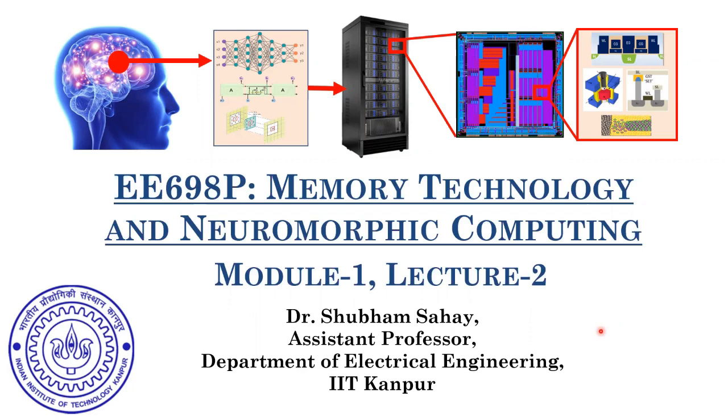Now, going ahead, we also talked about how the memory is organized within your conventional computing systems, such as your CPUs. We saw that, immediately inside your processing core, you have these fundamental units of memory, which are known as registers. All the registers are the fastest, and their physical size is the largest. What is small is their memory capacity. They are only available in some bytes, right? These registers are typically made up of more than 20 transistors, and hence their physical area is large. However, their speed is also the fastest.